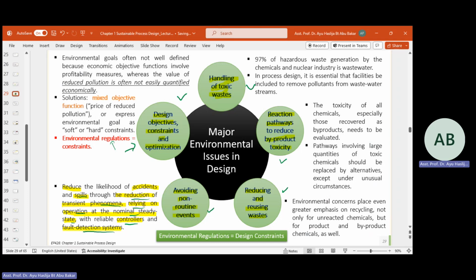Within the range, you must have your normal range. If the reading goes beyond the normal range, you need to start to check what happened to your process that it produced above normal range, not wait until the maximum limit.